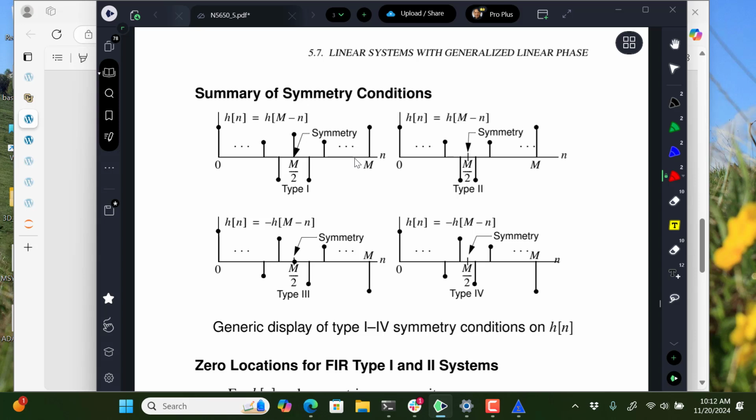So in the real-time DSP lab from this semester, I have tools in Python that will take the designs in Python, convert them to fixed or floating point FIR filter coefficient header files, and write those header files. And then in the microcontroller, you use those header files. And those header files were useful to me when I worked on a project at the previous company when I wanted to put it into an ARM core and delivered all this stuff to the guy that put it in the microcontroller or in the embedded system.